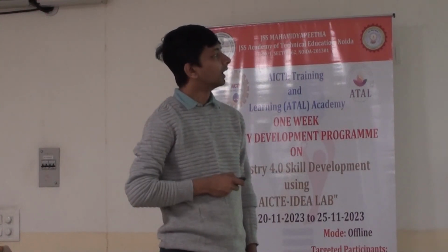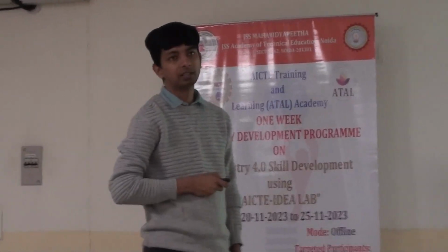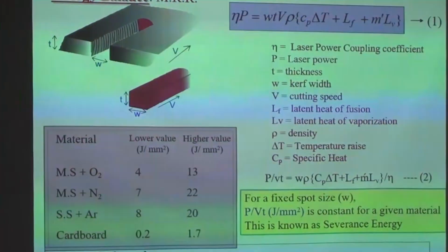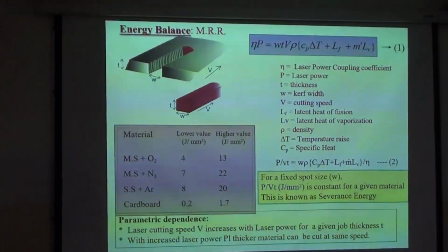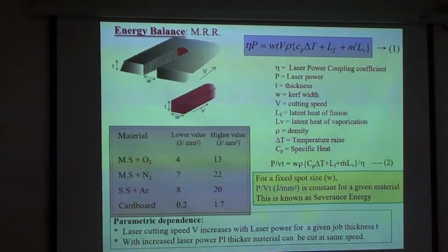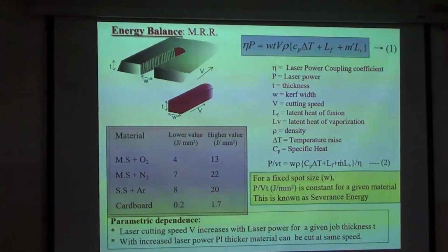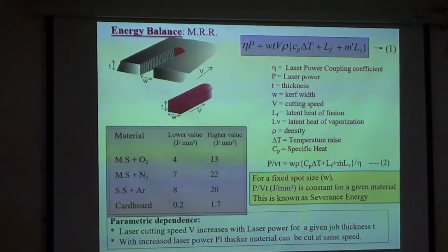So this is mass, and then this is Cp. Cp is basically the specific heat at constant pressure. So this Cp value is also available in literature. Delta T is the difference between the temperatures. So temperature means melting temperature, because here ultimately you need to melt, right? So melting temperature for steel is say around 1400 degrees Celsius. So 1400 degrees Celsius minus room temperature, which is almost equal to 1400 degrees Celsius. So delta T, you can put it as the melting temperature.